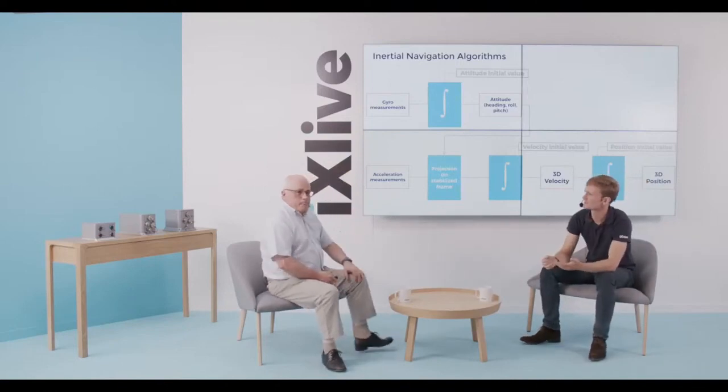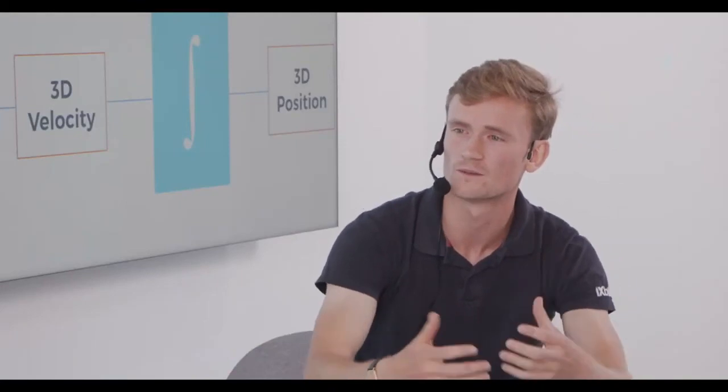Well, this is interesting because GNSS is correcting the position, but it will also have impact on other Kalman states. Yes, this is the magic of the Kalman filter. By just using a comparison on the position and by knowing the model of all the inertial sensors, we are able to compensate for some errors, like the heading error, even if we don't have a direct measurement of the heading. Okay. But when GNSS is no longer available, then this heading will drift. Yeah. So we may have some examples here of how it will drift.